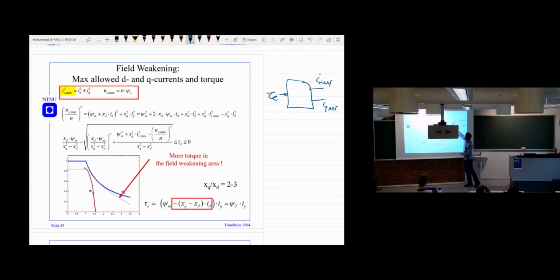We have the torque reference, and we have the stator voltage, and we have the maximum stator flux linkage. Based on that, we need to calculate the torque, d-axis and q-axis current reference. So once we have the d-axis and q-axis current reference, then we can implement the control. So so far we understand how to get the d-axis and the q-axis current reference. Once we know how to get these for this IPMSM machine, then we are now ready to implement the control, the current controller.